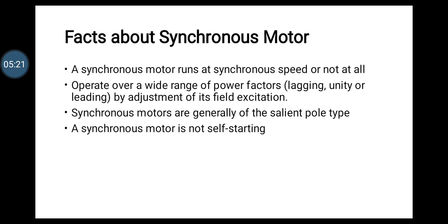Few facts about the synchronous motor. A synchronous motor runs at a synchronous speed or not at all. That means the synchronous motor either runs at the synchronous speed, otherwise it will not run. So the speed is constant, synchronous speed at all loads, otherwise it will not run at all. The only way to alter the speed is by changing the frequency, that means the supply frequency. That is the first fact.